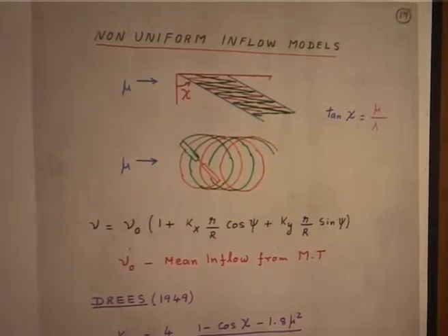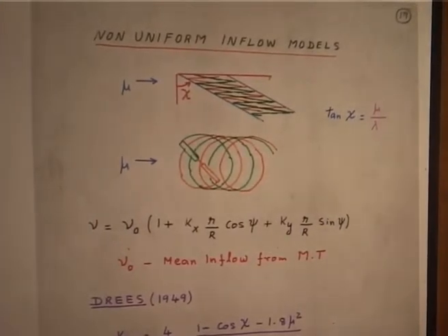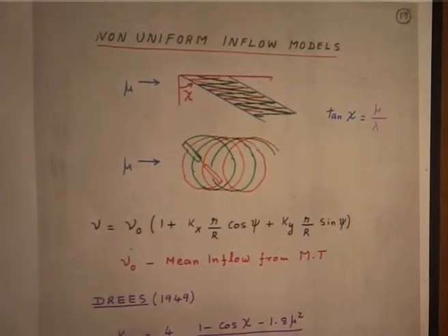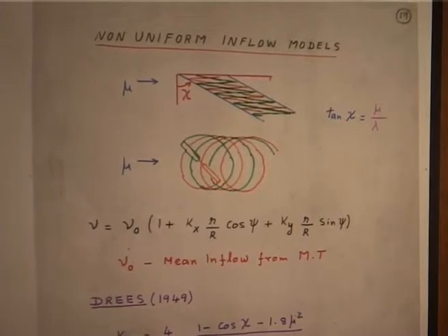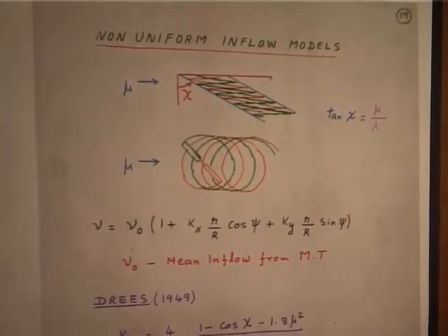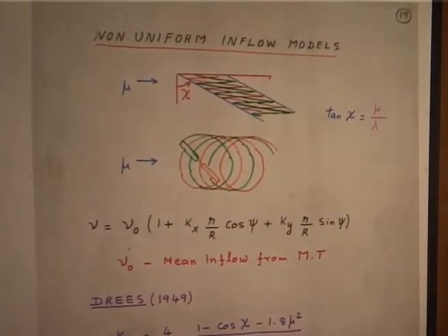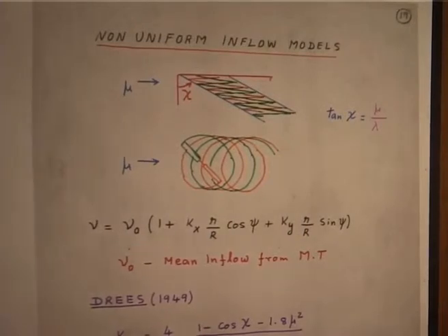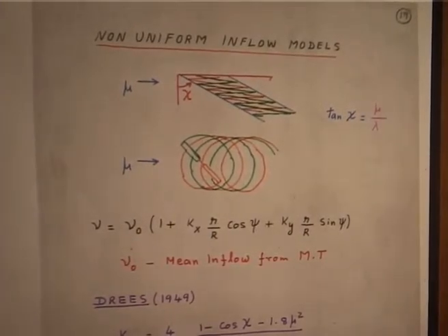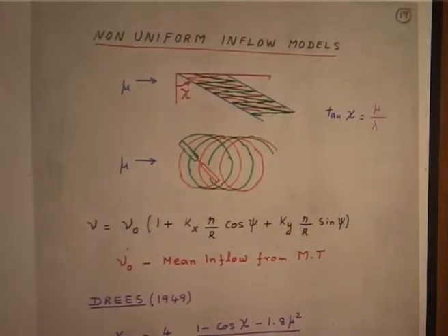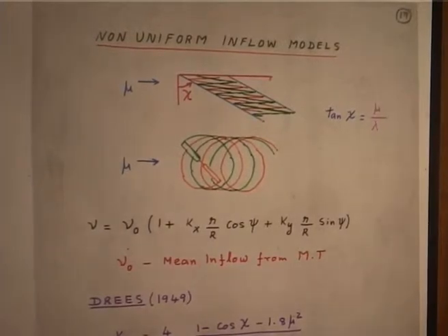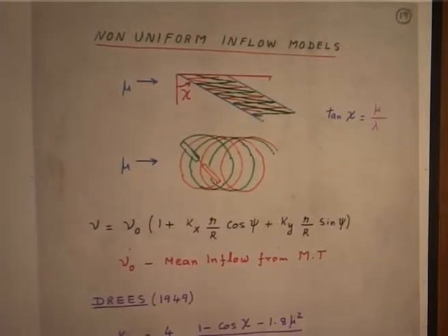Initially, I am just giving you a brief history of how you get the inflow, okay. It's a very interesting part. What you do is, you assume an actuator disc. Actuator disc means it has an infinite number of blades, and every blade is giving out a wake, so it is almost like a skewed cylinder, but assume uniform loading, gamma is constant, so it will be a semi-infinite skewed cylinder.